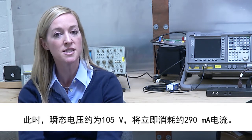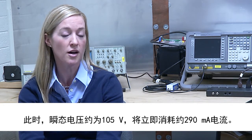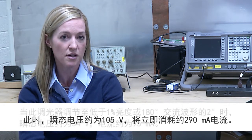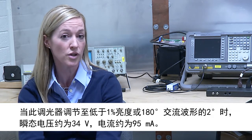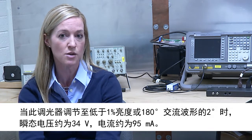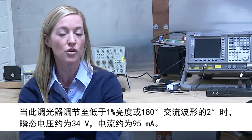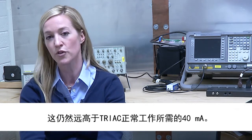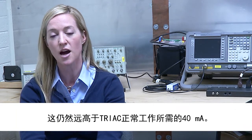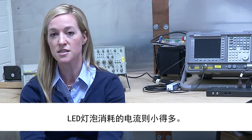At that point, the instantaneous voltage would be about 105 volts and would immediately draw about 290 milliamps. When the dimmer is turned down to about 1% on, or 2 degrees of the 180-degree AC waveform, the instantaneous voltage is about 34 volts and current is about 95 milliamps. This is still well above the 40 milliamps needed for the triac to operate correctly. An LED bulb draws significantly less current.